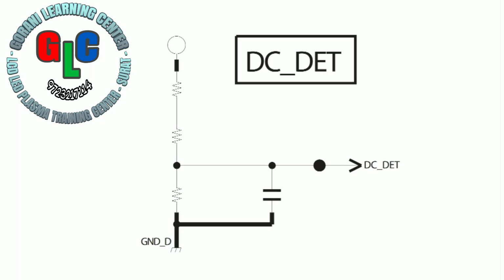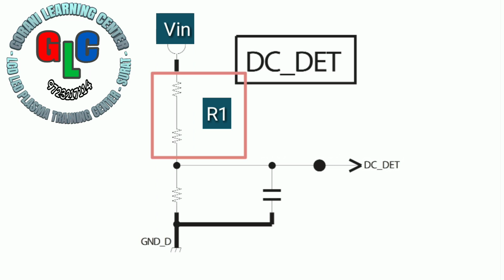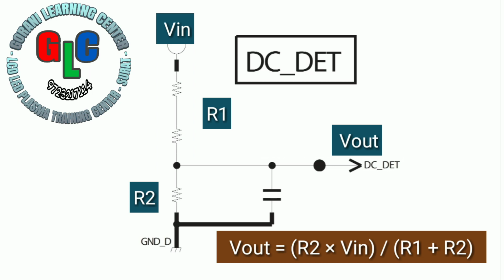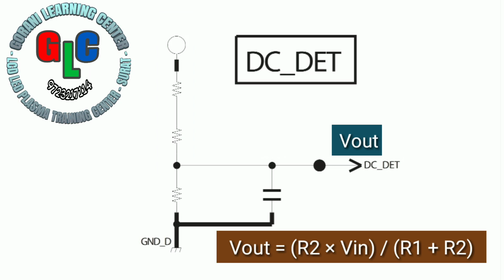They use two types of power supply, external or internal. The external power supply has 19.5 volt and the internal power supply has 12 volt for main power. The method to calculate the main power reference uses this simple equation, to calculate V out for reference to detect an error in the main power section.